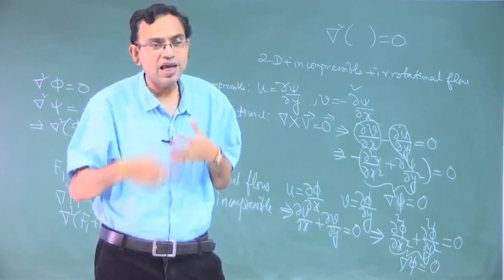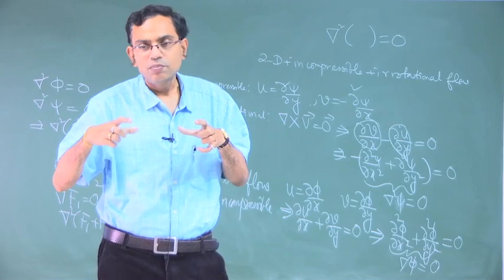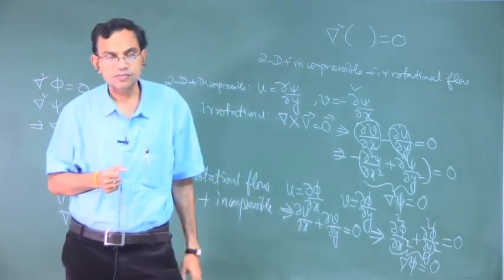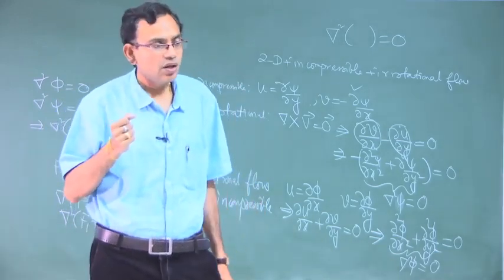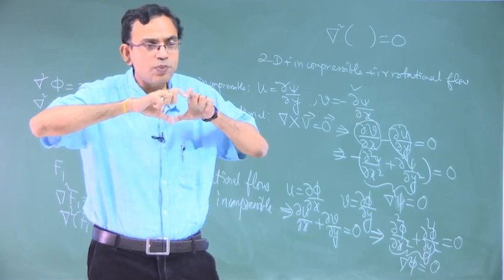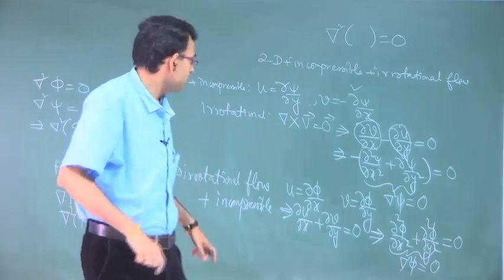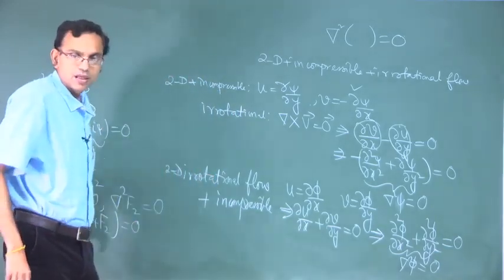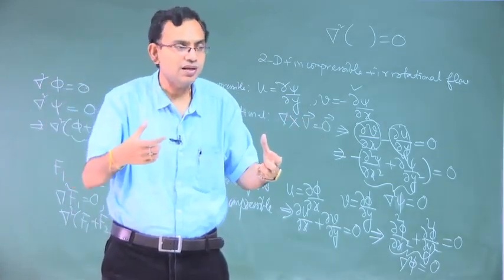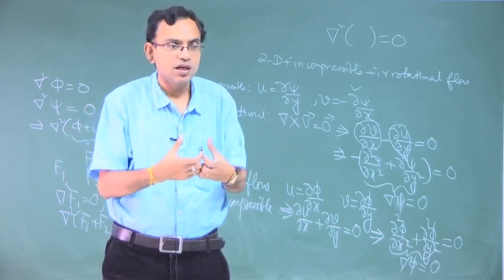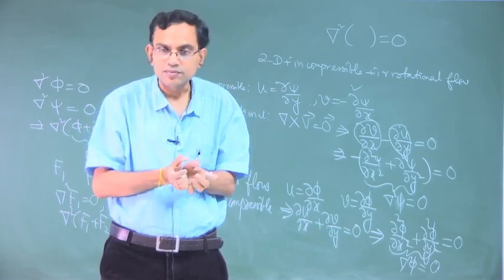So, for example, if we say what will be the nature of potential flow past a circular cylinder. Okay. So, to understand that we can make a superposition of certain simple elementary types of complex potential F, superimpose them together and try to obtain a contour of a body which looks like a circular cylinder.